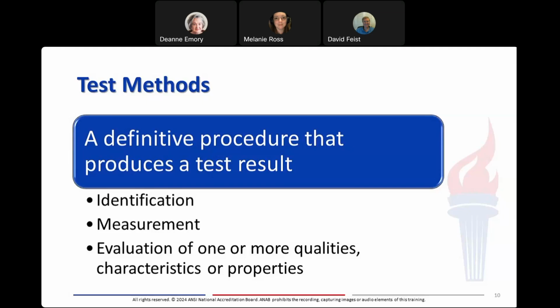An ASTM test method typically includes a concise description of an orderly procedure for determining a property or a constituent of a material, an assembly of materials, or a product. The directions for performing the test include all the essential details as to the apparatus, test specimen, procedure, and the calculations needed to achieve satisfactory precision and bias.